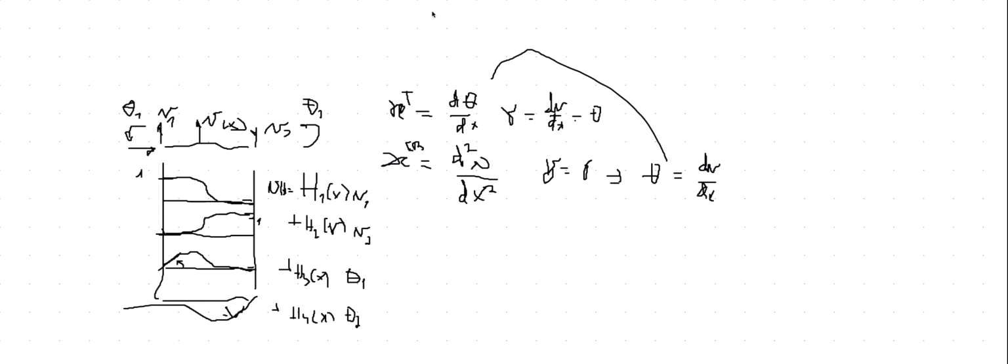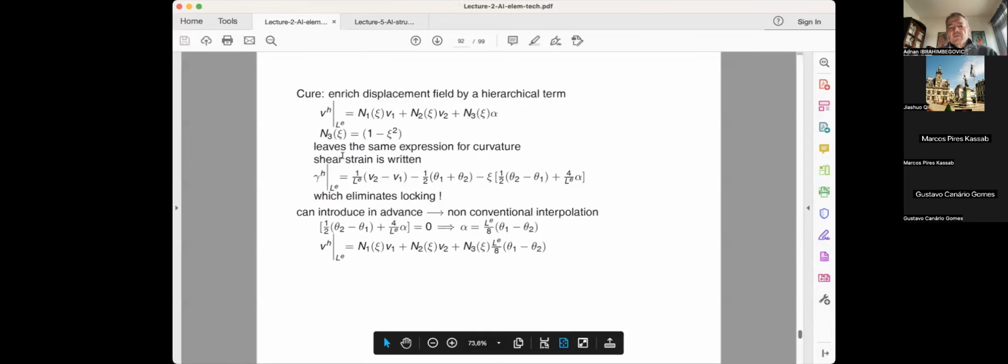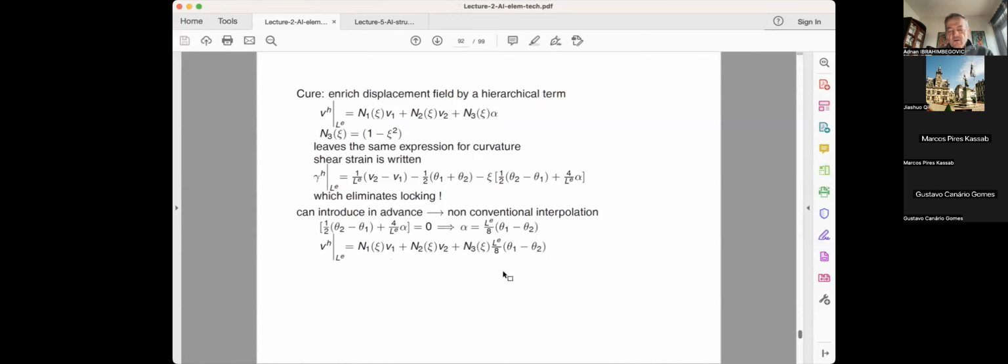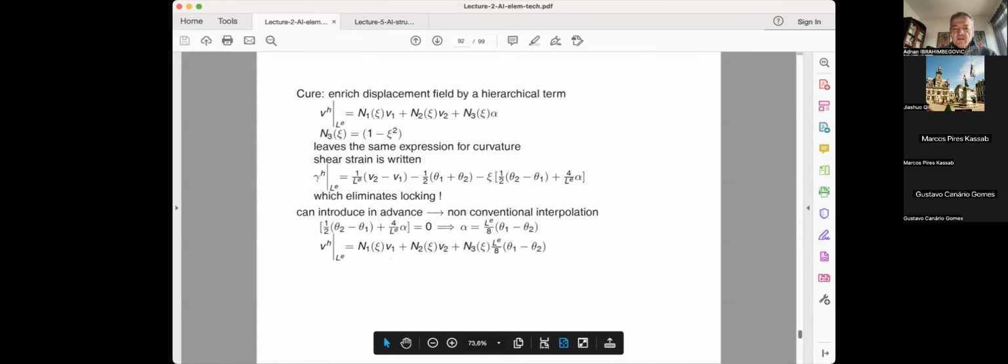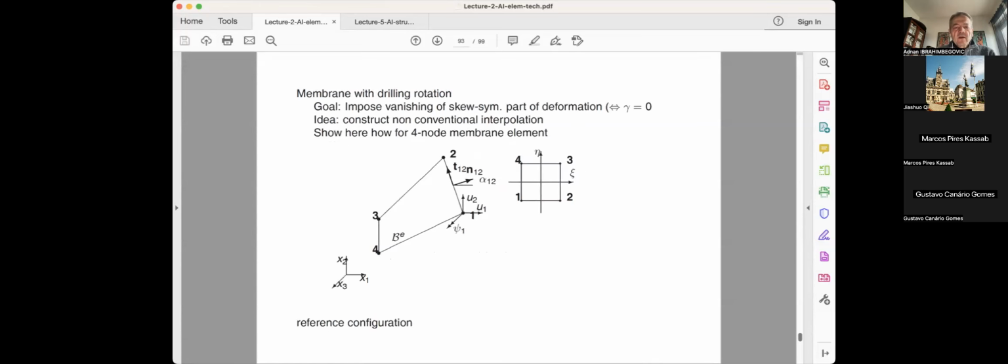So you can reproduce all this with the Timoshenko beam, and that's actually the direction we are going, by using this type of interpolation where the transverse displacement field is not only a function of the nodal value of the transverse displacement, but also of the rotation. But of course, the interpolation gets a little bit more complicated than isoparametric interpolation, but that's what the structures are requiring. They have reduced models, so reduction is certainly something that you have to take into account and accommodate this locking phenomenon and do the proper modification.